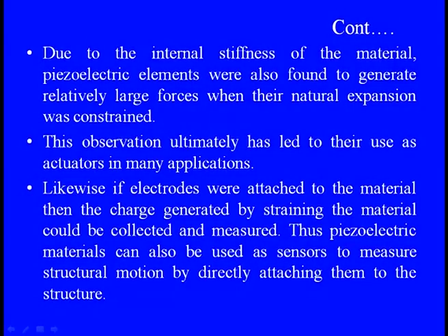When we look at the basic features, there are two main things. One, due to internal stiffness, piezoelectric elements generate relatively large forces when their natural expansion is constrained. This observation ultimately led to their use as actuators, because whenever the internal stiffness is affected by voltage changes, a large amount of reactive force comes out. So you can actuate the material by changing its internal stiffness.